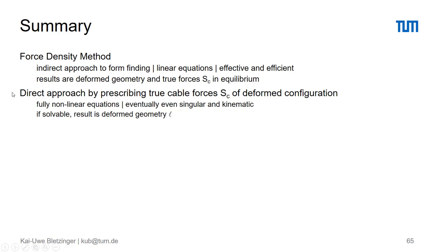In contrast, we call it the direct approach if we directly prescribe the true cable forces of the deformed configuration in equilibrium. The consequence is that we receive fully nonlinear equations, which eventually are even singular in kinematics. If we can solve them, the result is the deformed geometry.